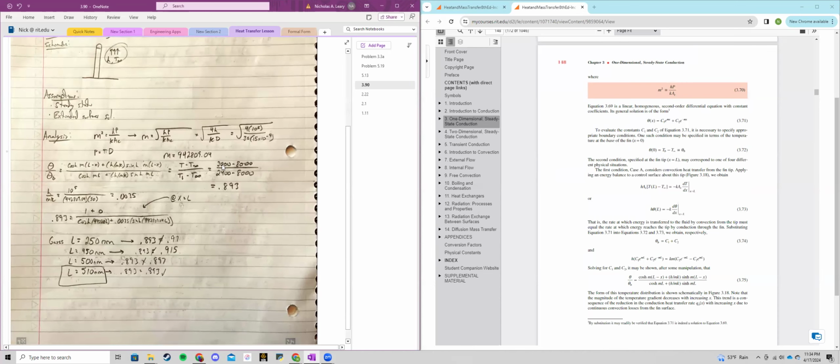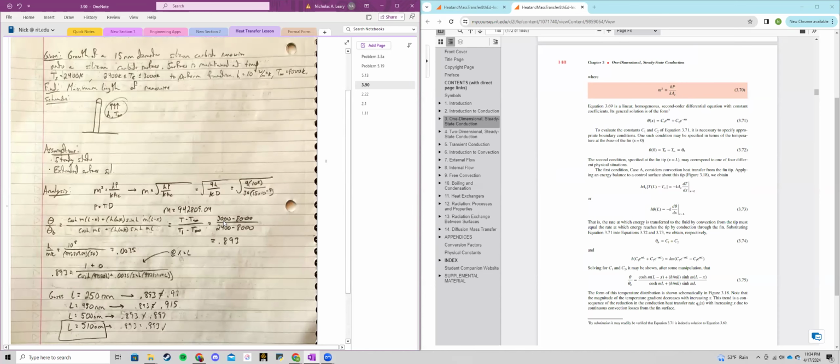So we know that our range of temperatures, we've got to stay within the 3,000 and then also the 2400, subtracting the ambient temperature, is equal to 0.893. So that will be equal to all of this over on the left side where my cursor is. Just to solve in steps, I solved for h over mk, which I got a value of 0.035.